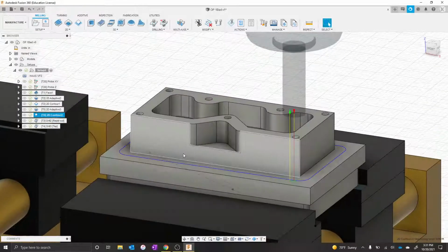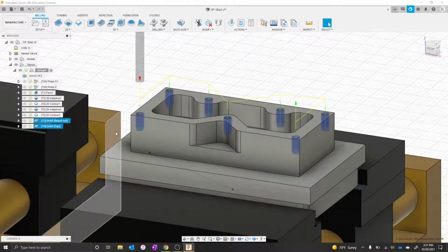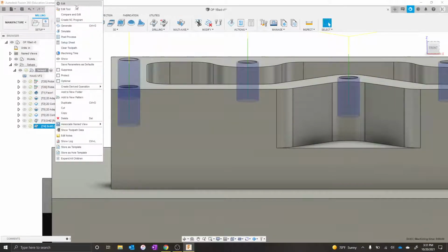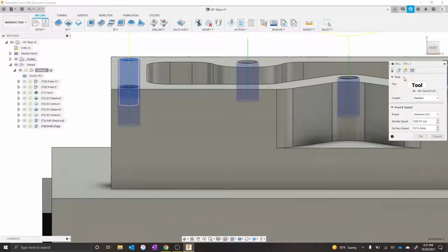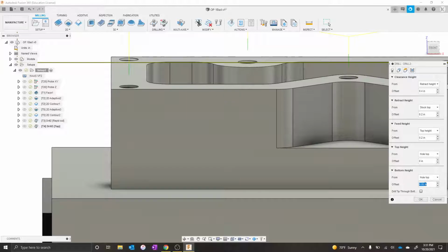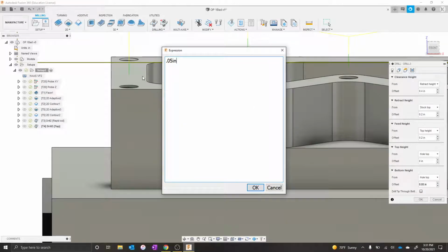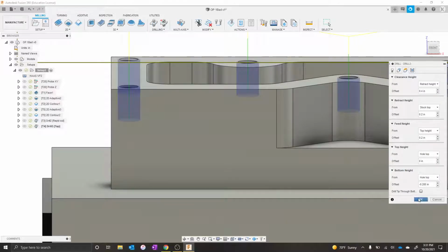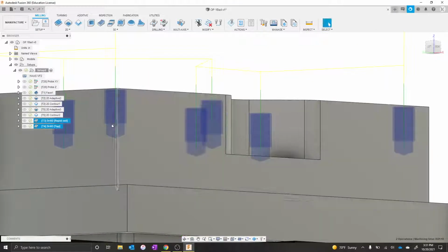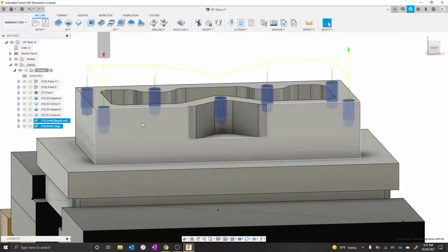Another thing to be aware of is the distance we can tap downwards. We might not even want to go this far. The recommended tapping depth is at max 1.5 times the diameter of the tool. So from the hole top, edit expression, instead of 0.05, we can go minus 1.5 times tool_diameter. That'll give us a better tapping distance. It's better representative of what we can actually reach. It's pretty close, but it gives us a more safe tap.